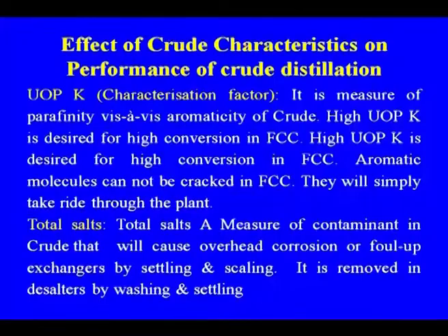Total salts will cause overhead corrosion and fouling of the exchangers. Some of this may be by settling or scaling. It is removed in the desalter by washing and settling. So, knowing the total salt amount matters: if the salt content is higher, then the operation of the desalter has to be more severe, not meaning the temperature, but a more effective removal of the impurities.